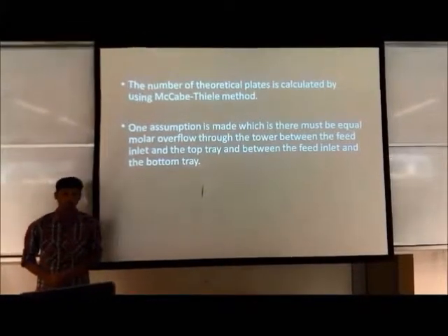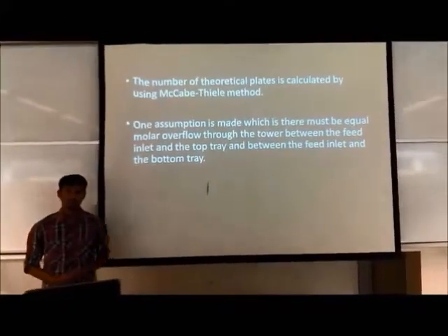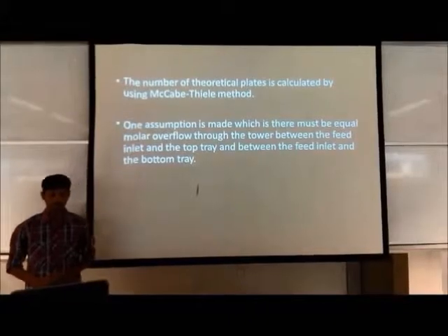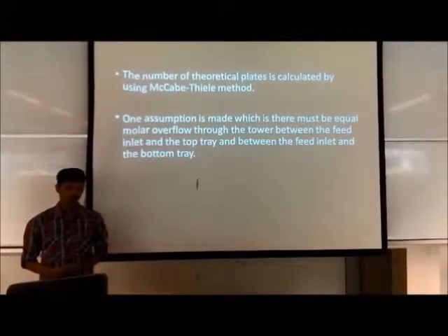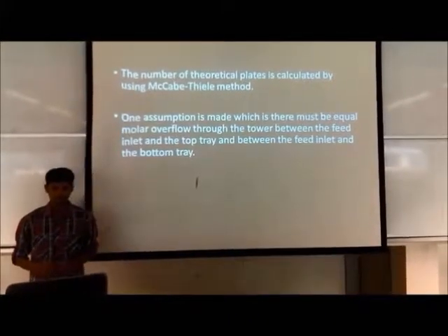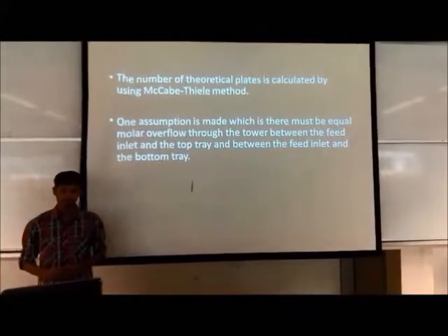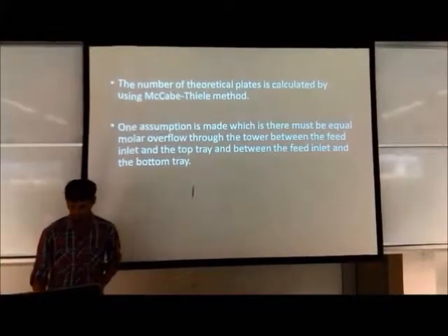Moving on, the number of theoretical plates is calculated using the McCabe-Thiele method. One assumption is made that there must be an equal molar overflow through the tower between the feed inlet and the top tray, and also between the feed inlet and the bottom tray.